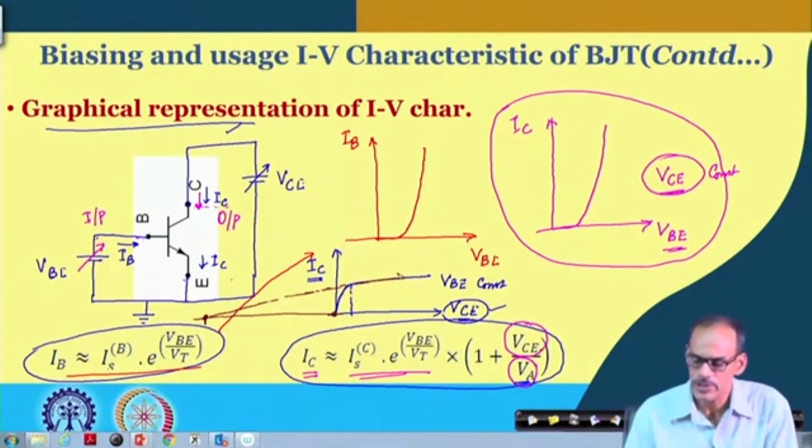Now, if you see the graphical interpretation of the IV characteristic, they do have other meaning also. Presently, whatever characteristic we have plotted, we have changed VCE and VBE to quite a large extent, pushing the device into the heavily saturated portion. Namely, we are seeing highly nonlinear effect from here to here. Likewise here also we can see highly nonlinear effect.